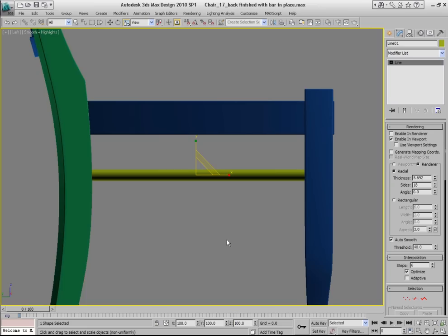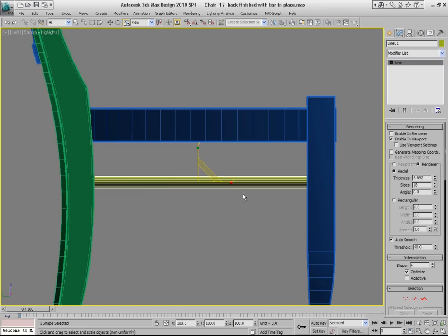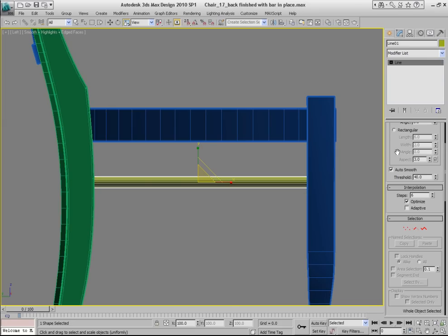So go back to 3ds Max, and before we can taper it, we need to subdivide it along the length. And the quickest way would be right here on the Modify panel for the editable spline object, to uncheck this Optimize checkbox and increase the number of steps so that we give it somewhat more vertical edges dividing this object. So I guess 23, maybe 24 would be good.